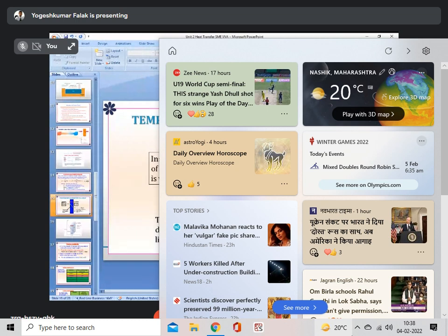See this one. Inside it is warm, 298 Kelvin, and across some thickness, the blue thickness, in the direction of flow, it is about 273 Kelvin. So heat flows in this direction, the outside is cold, and the temperature distribution is linear, right? It falls linearly. So Q is equal to minus kA (T out minus T in) by L. Also, students, note down this formula, in which K is the thermal conductivity in watt per meter Kelvin, T is the temperature in Kelvin, and Q by A is the heat flux.